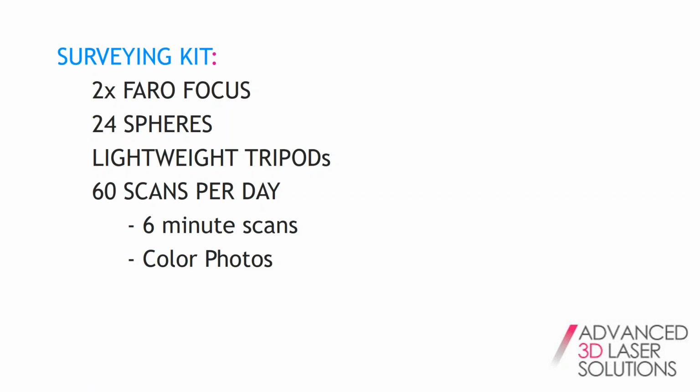So for this particular job for the pharmaceutical firm, we went in with 2 of the Faro Focuses. We had about 24 spheres because the particular area we were surveying was really congested. We just knew that we'd have to put quite a tight knit of spheres down to make sure we could get in as many scans as possible.